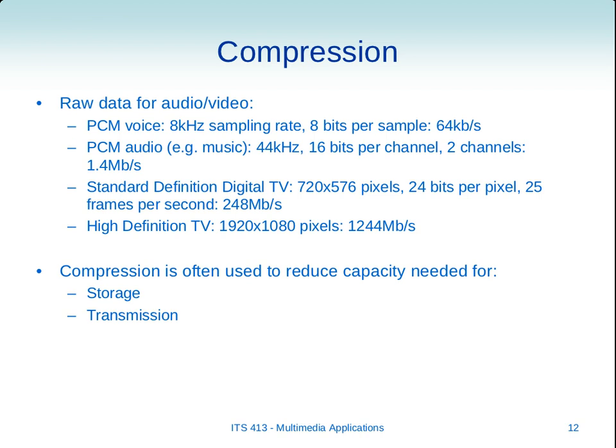So on a CD, which is about this size, 700 megabytes, you can fit about 70 minutes of CD quality audio recorded on there. Because in CD, the typical audio quality is a sampling rate of 44 kilohertz, stereo, 16 bits per channel. And in fact, that's specified in the standard for CDs, or audio CD.